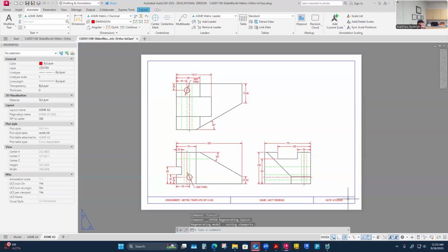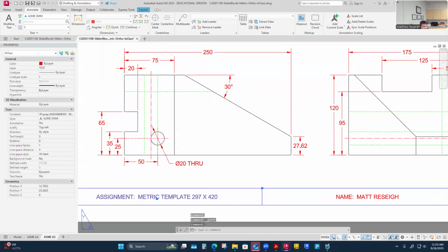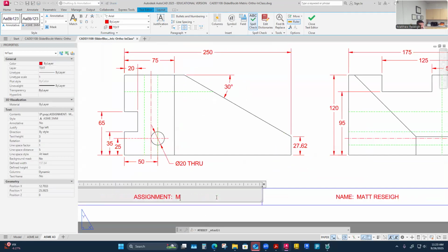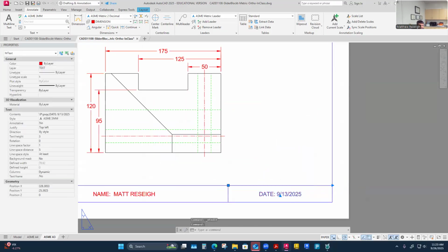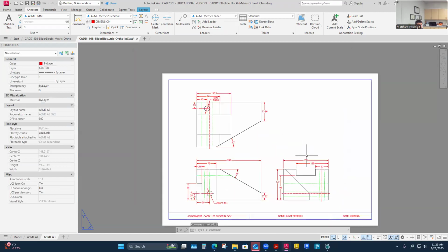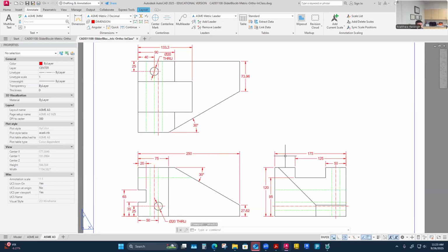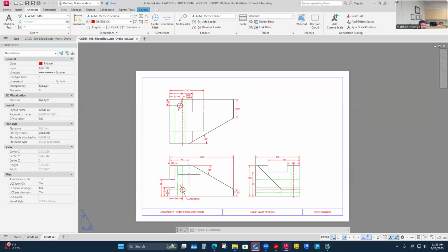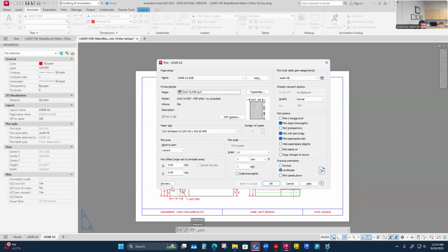I'm going to jump back out and take another look. I did all my line type scale adjustment, maybe potentially on the wrong sheet. I need to hit save. I haven't hit save in a while, but this thing is getting to the end here. Date that. 26. I still think I'm okay. I don't mind those line type scales. They're good. It's all done. Maybe I'll do a Control P plot, see how it looks.